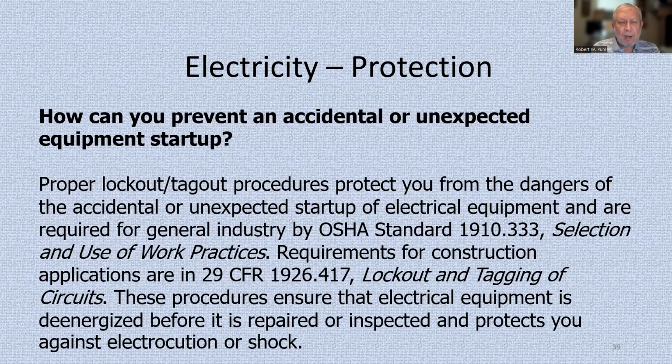insulated. Proper lockout tagout procedures protect you from the dangers of the accidental or unexpected startup of electrical equipment and are required for general industry by OSHA standard 1910.333, selection and use of work practices, which we also got to cover. Requirements for construction applications are in 29 CFR 1926.417, locking and tagging of circuits. These procedures ensure that electrical equipment is de-energized before it is repaired or inspected and protects you against electrocution or shock. And this lockout tagout standard in 333 is not much different from the one in 1910.147, lockout, which we've covered before.